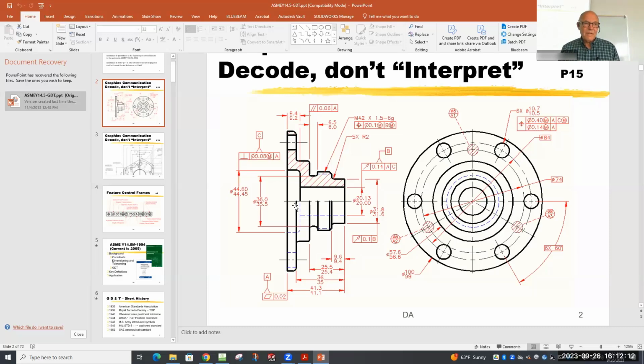It's called the surface plate, and machinists love their surface plates. If you ever get caught putting a coffee cup down on one, you'll get slapped, because they protect their surface plate by covering it up all the time. They don't want anything on that surface plate. They don't want anything sticky on there so the part doesn't slide. And God forbid you ever put a hammer on it. You drop a hammer on a surface plate and you're going to get fired. That surface plate was how you determine what was right.